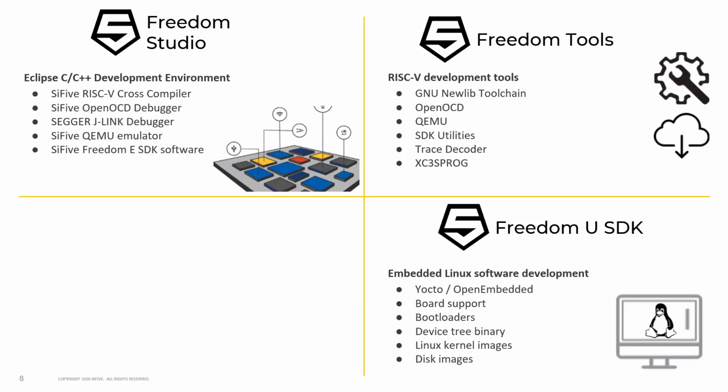I might have mentioned this earlier, but the SiFive RISC-V Core IP offering ranges from small single-issue 2 to 3 stage pipeline cores typically found in microcontrollers or subsystems, all the way up to dual-issue 8-stage superscalar pipeline application processors running Linux. Software support for the application cores running Linux comes from the Freedom U SDK. Based on Yocto, this allows you to layer your dependencies and create your own embedded Linux distribution. There are rootfs images attached to each release for our development boards, or you can check out and build the software yourself and extend it based on your needs.